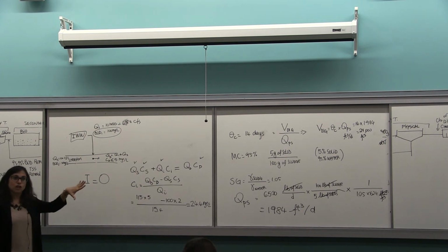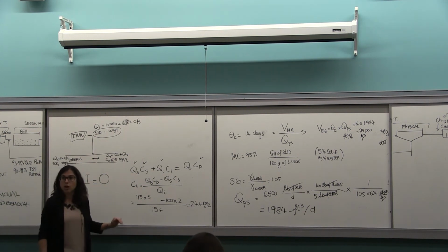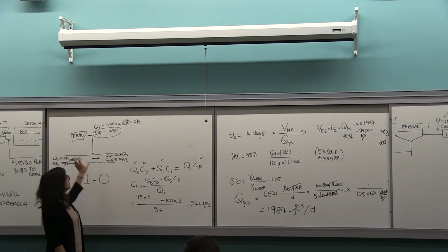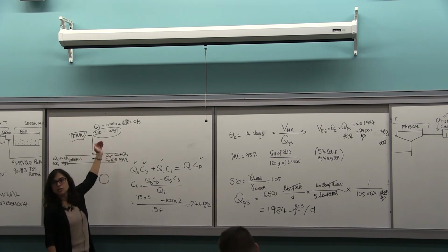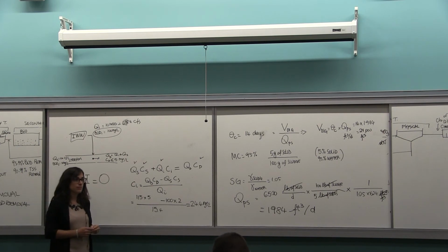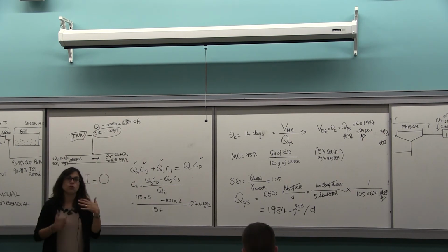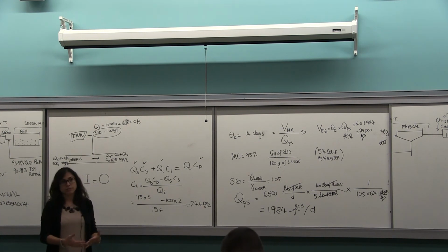Usually for discharge in a river, it's either a BOD limitation or a dissolved oxygen limitation. It's the same equation, it's just that you have dissolved oxygen instead of BOD. So those are the important parameters. You don't want to add organic loading, and you don't want to reduce the dissolved oxygen of the stream.